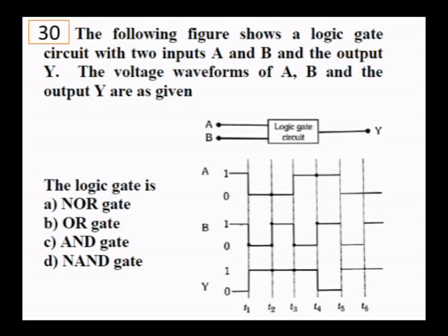This is a timing diagram. You have to see how exactly in every particular time interval the signals are taken. Now this is 1 high and high. For high and high you are getting nil, that is 0. So you can write it like 1 and 1, you are getting 0. And go to the next time interval, 0 and 0 you are getting 1. And next time interval, 0 and 1 but still 1. And the next one, 1 and 0 but still 1.